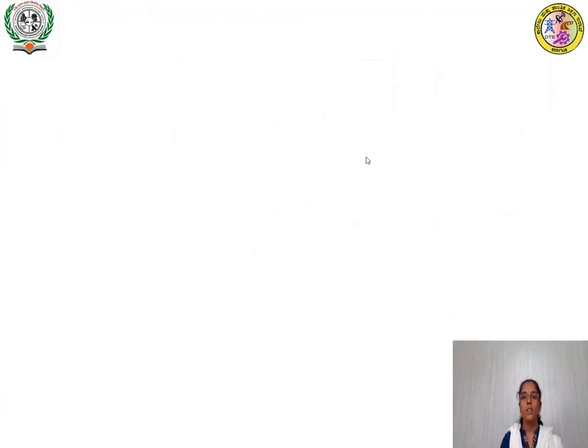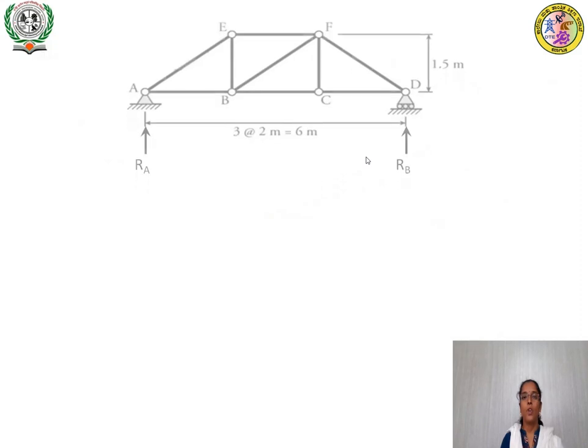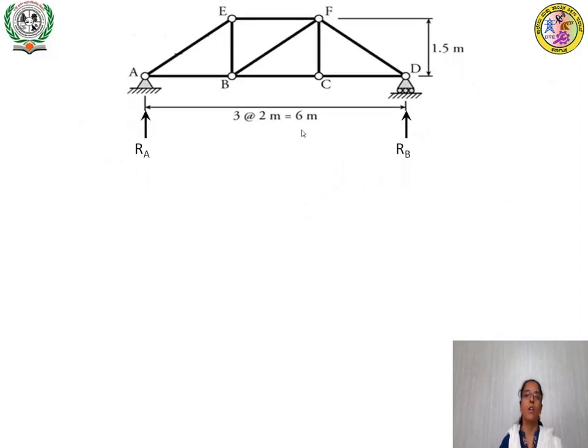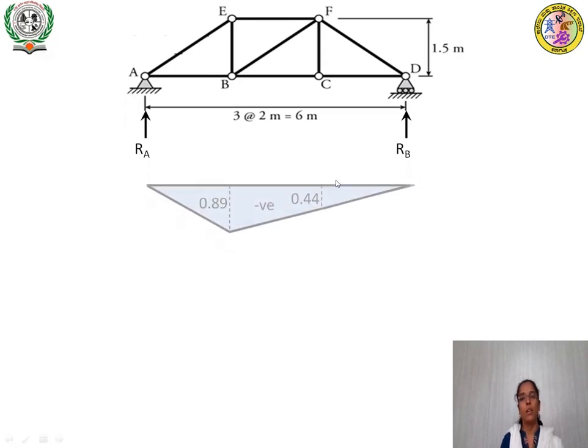While solving a given problem, as we have drawn in case of shear force and bending moment, we will be drawing the given loading diagram first, then shear force, then bending moment, and then deflected shape, like that. So, here also while drawing the influence line diagram, you have to draw one below the other, like this.